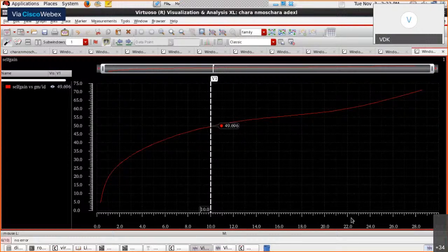Bandwidth, expressed in terms of cutoff frequency in radians per second, omega, is always equal to the reciprocal of the time constant that defines the pole in a transfer function. So to maximize the bandwidth, we need to minimize the time constants that define the pole locations. We require smaller RC time constants.